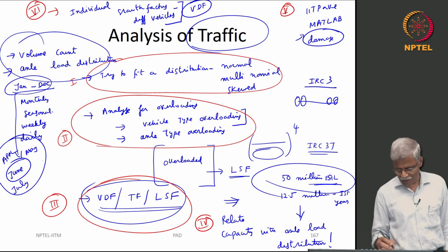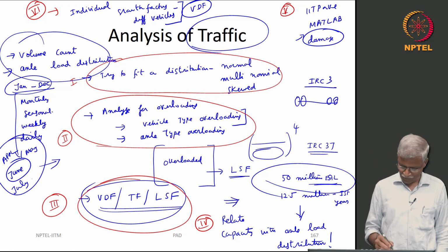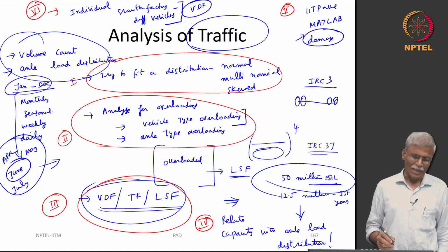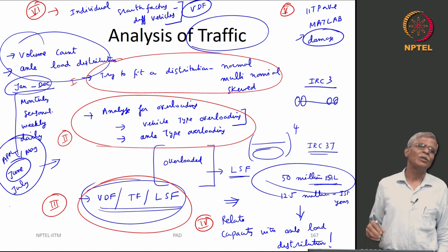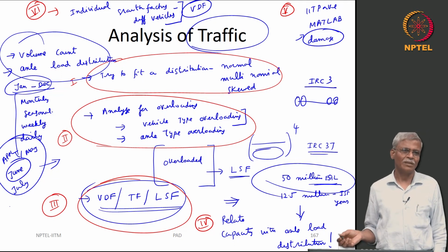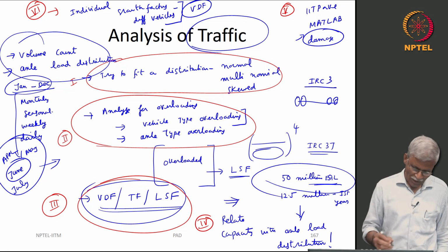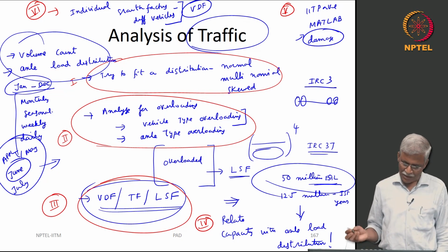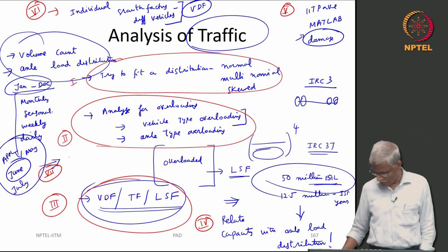So, you may want to say that I will worry about the distress equation only for these 4 months as far as rutting is concerned, and in the months of, let us say, October, November, December, January, where the temperature is low, I will use that information for fatigue. Those kinds of splitting up also one can do. I will just call that 6, 7. So, as of now, these are all the things that you can really look for.